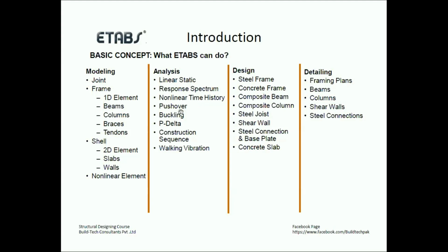Like you sometimes need to go for a pushover analysis, which is static but a non-linear method. Then there are response spectrum and time history analysis. All these different kinds of seismic analysis can be performed in ETABS. Then we go for the design process. Once the analysis is complete, the next stage is the design.